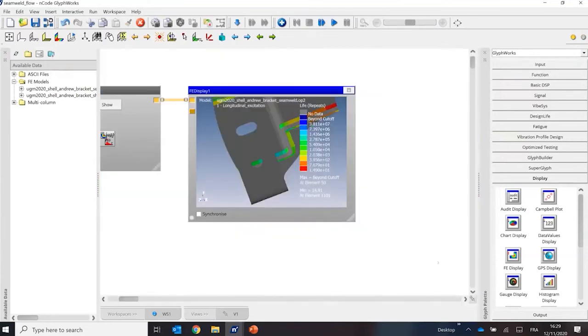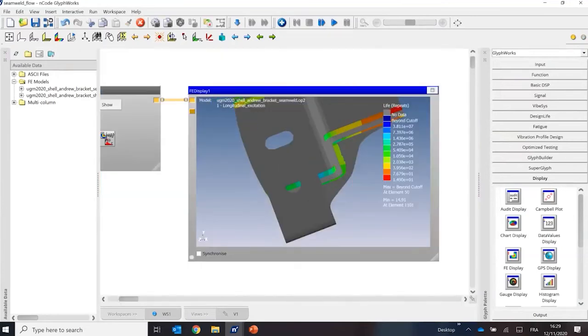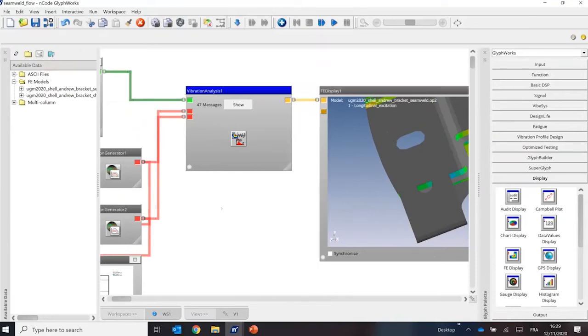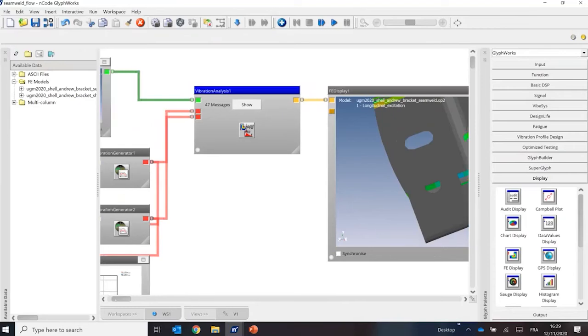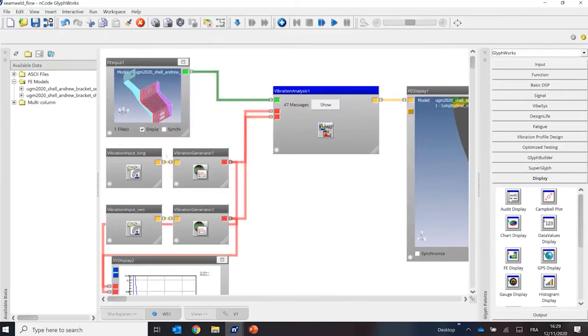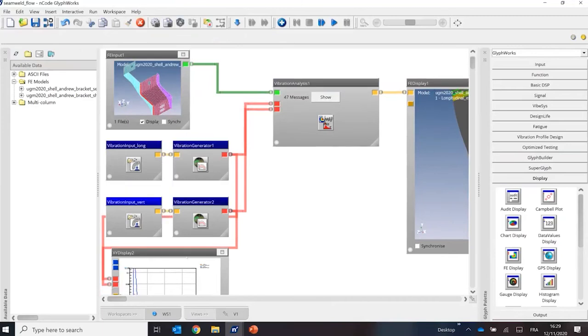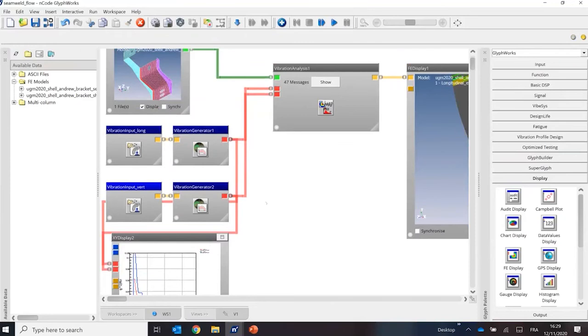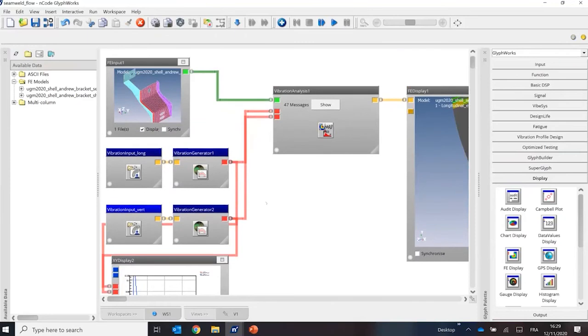You've got tables of results associated with that. Obviously, you can change the material. You get loads of fatigue properties you can set up in this glyph. I won't enter into much details here, but just to show you again, the sort of things we can do in the same interface, meaning that this PSD, which is currently coming from the standard, I could have used the PSD I measured instead, or the envelope that I just calculated, right? So it's very, very flexible.